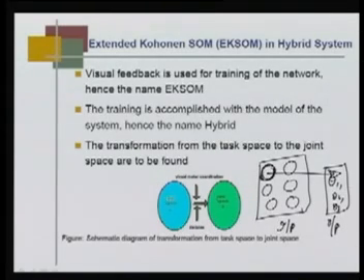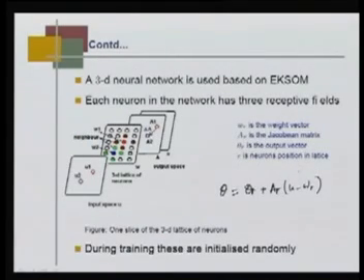And how do we do it? You know that the relationship between the input space, the camera image plane coordinate, and theta is actually nonlinear, but this we can assume to be linear in the discretized cell. That is the objective. So, this is what is done here: this is my 3D lattice, this is my u1, camera 1 coordinate, camera 2 coordinate, each coordinate gives you xf and yf, xf and yf.